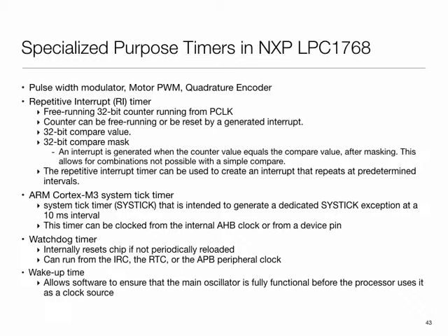It gets used in power supplies. Switching mode power supplies are basically operating on PWM signals. They also get used in other places like brightness control in LEDs, LED lamps that you get. They usually come with an LED light controller. They're usually operating on this principle. So it is very commonly found in a variety of embedded applications because it's a very cheap way of conveying analog information.